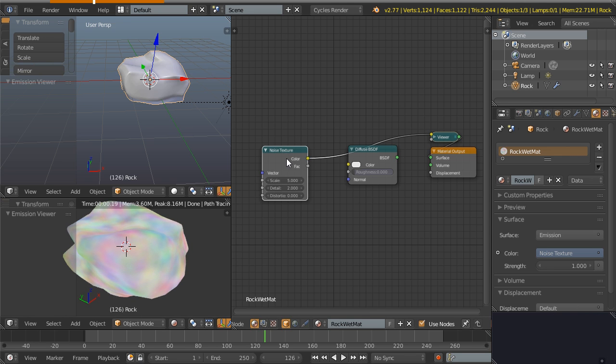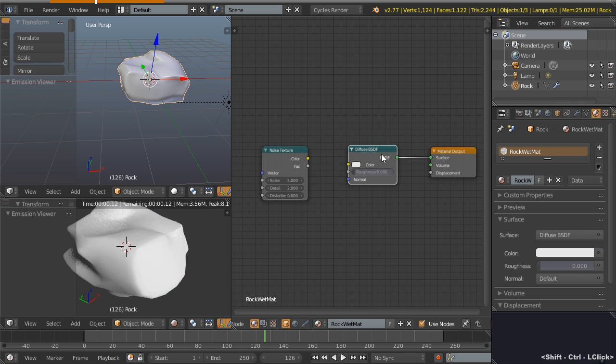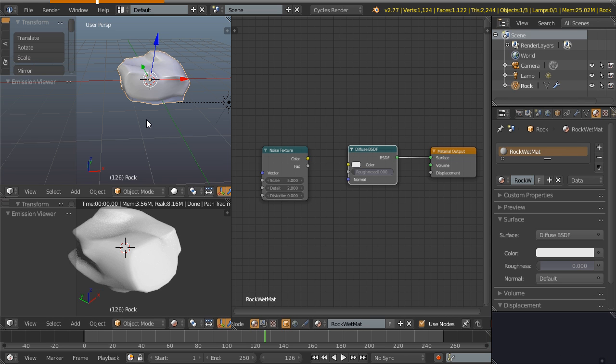And also we can go Control Shift again on the node and just keep toggling through the various outputs there. So we're going to find that pretty useful, and then we can just Control Shift click on this, and it removes everything and sets it back the way we want. So this is a great setup for us to now work on our rock material.